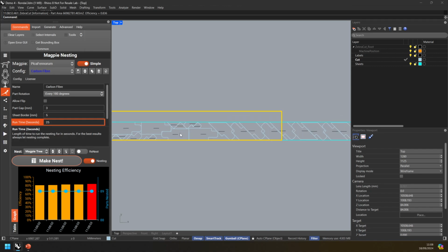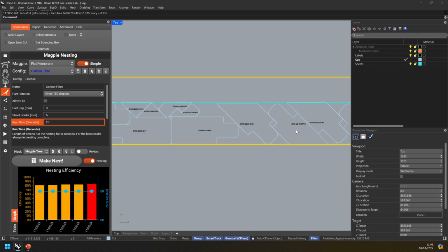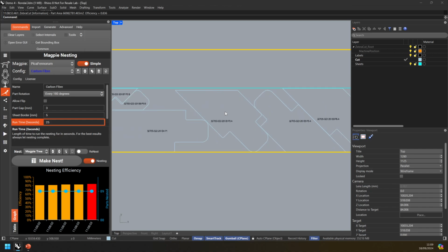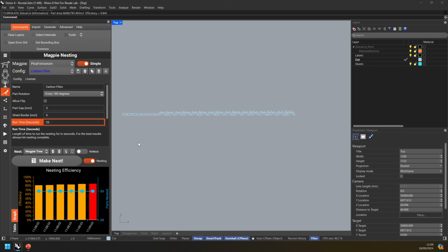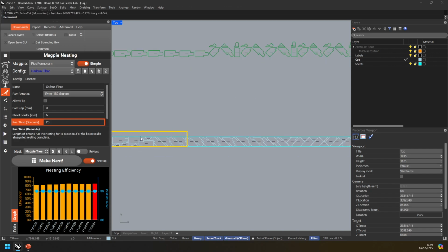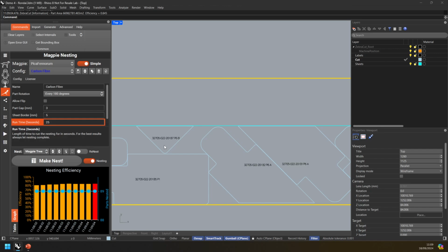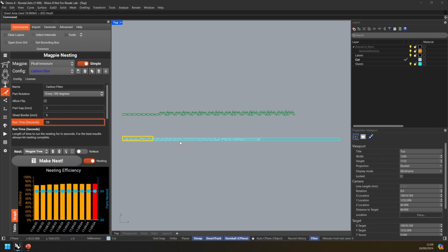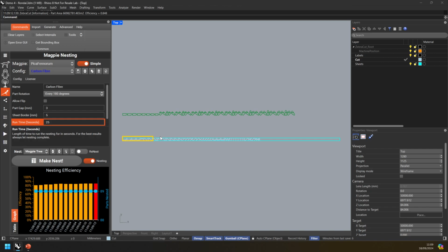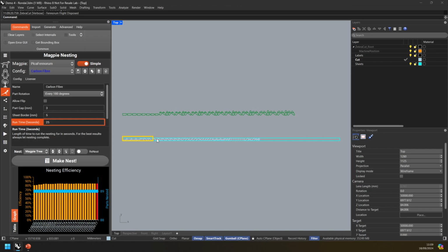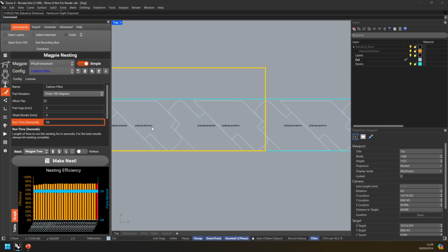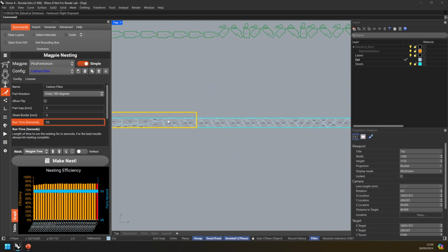Also, these nests will improve over time. You can see the parts do fit nicely and why they had to be chopped. There's no way you'd fit that in otherwise. All your parts are labelled, so you'll know which ones are which and how to put them back together again. If you want to keep track of how many parts they're broken into, you can have 1 of 3, 2 of 3, 3 of 3, or even A of C, B of C, C of C, if you want to keep track of it in that way. It just depends how much inkjetting you're willing to do.